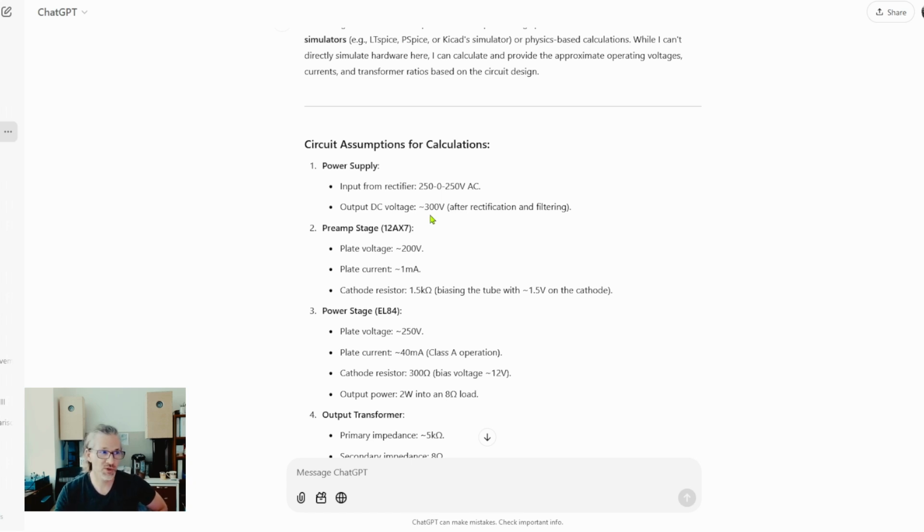you might think 10% is not that much, and I can tell you, yes, tube designs can easily handle 10% differences. But if you build your tube design to be maxed out at 300 volts, running your tubes at 100% plate dissipation at 300, then adding the 10% significantly shortens the lifespan. You would think the vast majority of commercial tube amplifiers have been designed by AI, because a lot of them are running like that.